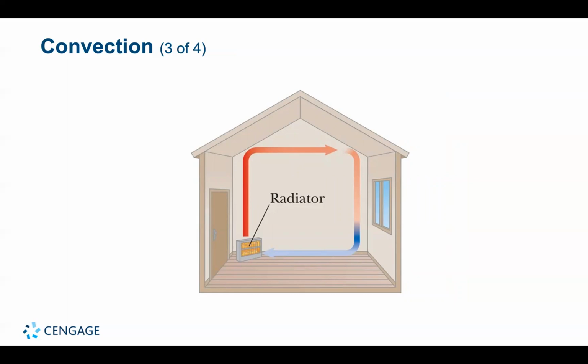An automobile engine is maintained at a safe operating temperature by a combination of conduction and forced convection. Water, or rather a mixture of water and antifreeze, circulates in the interior of the engine. As the metal of the engine block increases in temperature, energy passes from the hot metal to the cooler water by thermal conduction. The water pump forces water out of the engine into the radiator, and in the process carries energy along with it.